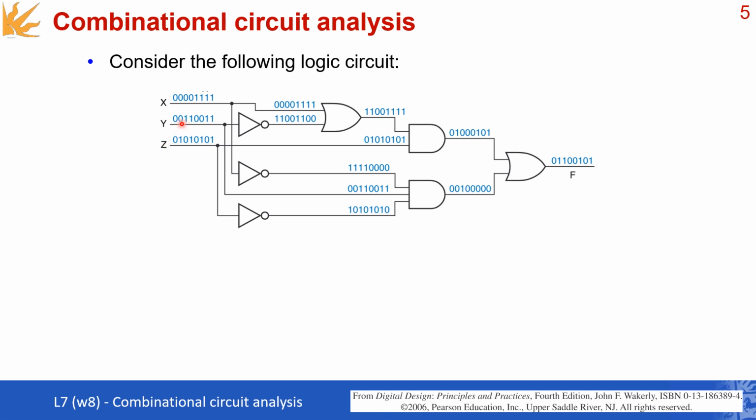So for these 4 bits, the first half, these 2, you make them 0, and the other 2, you make them 1. And then you repeat again, 0, 0, 1, 1. And for the last variable, you got only one option, which means 2 to the power of 1, 2 options. So you concentrate on the first 2 values. Half of them being 0 means the first one is 0, and the other one is 1. So you repeat the pattern 0, 1, 0, 1, 0, 1, up until you have 8 different inputs. And then it's straightforward.